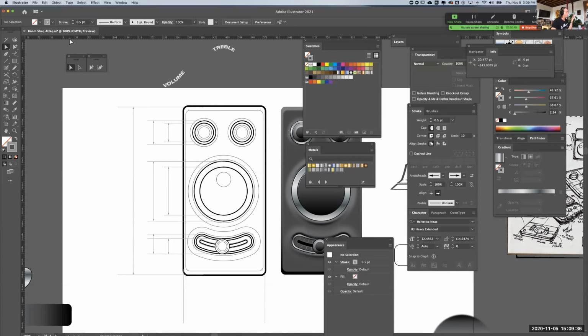So let's say you have the rulers right now, but all these dimensions are in points, which I don't have a clue what a point is. So I right click on this ruler, and it goes for both of them. They both change. Right click on it, and then I'm going to go now with millimeters. All right, so now I should be able to click on that. Now, width, height, 167.